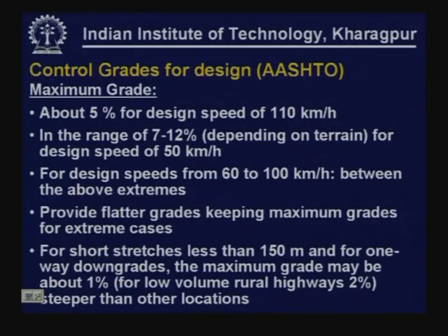Now, there is certain relaxation. For short stretches less than 150 meter and for one-way downgrades, the maximum grade may be about 1% steeper than at other locations, and for low volume rural highways, it may be even 2% steeper than at other locations.